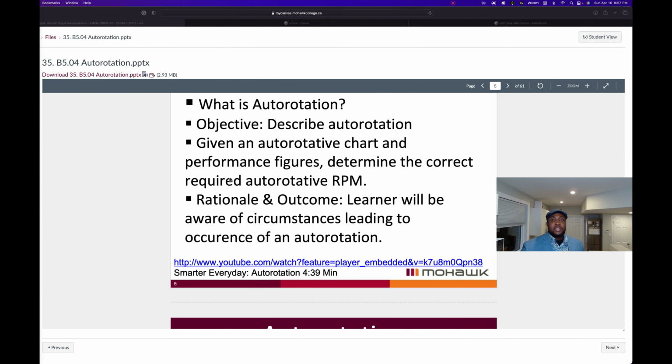The next phase of flight, after we have lowered the collective lever and the pilot has aviated and flown the aircraft, which is what you're always supposed to do, is to perform an autorotation flare. To slow the rate of descent prior to touchdown, the cyclic is moved aft or rearward. This increases the total lifting force of the rotor and reduces the helicopter's rate of descent. Rotor RPM increases due to the greater volume of air acting on the rotor disc during a flare.